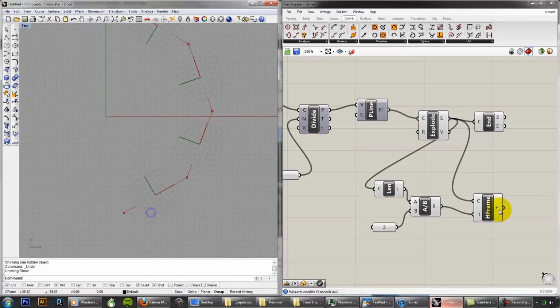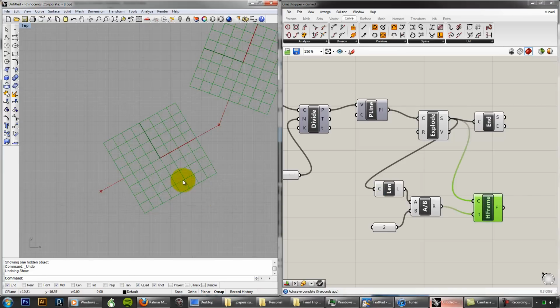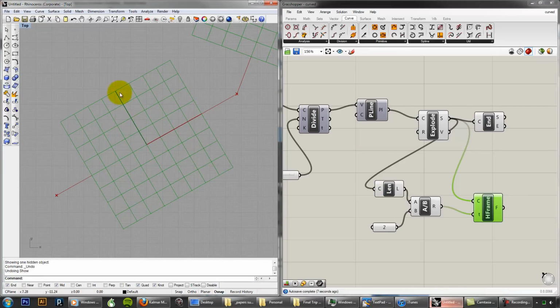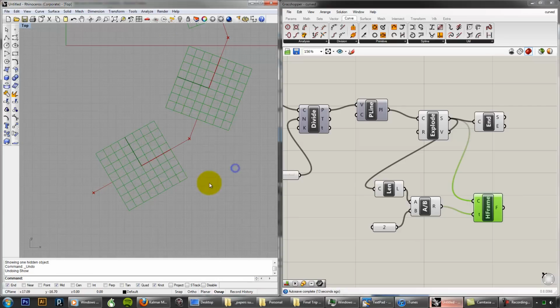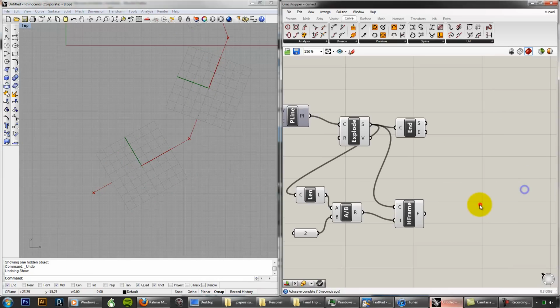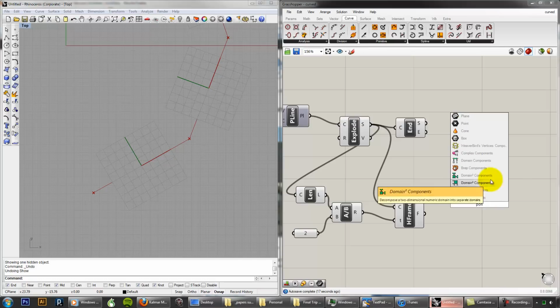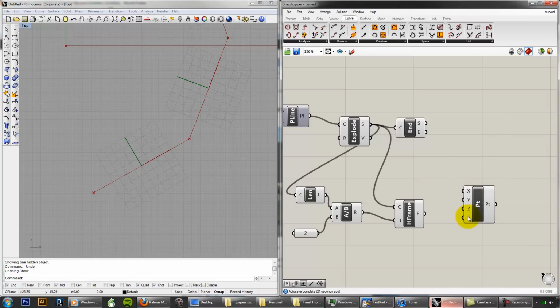And the interesting thing about creating a frame, as I showed in the other example, is that a frame is a local coordinate system. So this is y, and this is x. And so if we want to move something in the negative y, that's going to give us that last point. So I'm going to go ahead and take a point object, point x, y, z. Plug in the frame for s because we are changing the coordinate system.